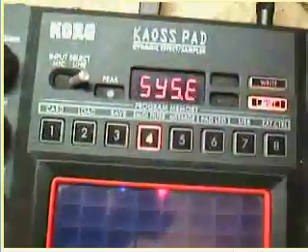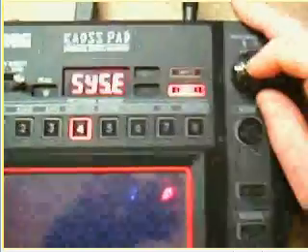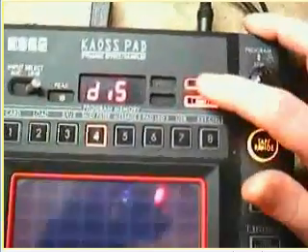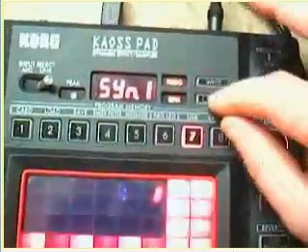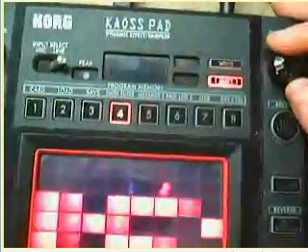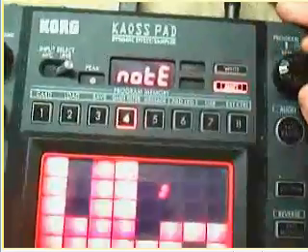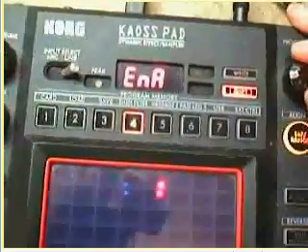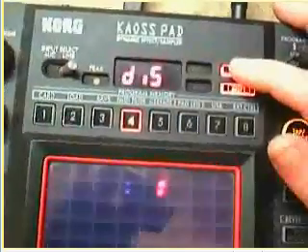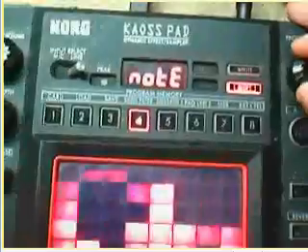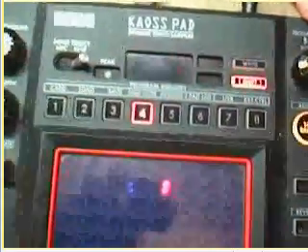In this case, I would recommend disabling everything except what you need. So go ahead and press the knob down on System, switch it over to Disable, and press Right. Then you're going to have to go back in, Shift 8, Shift 4, go to Note, or whatever comes up next on yours, push it in, and change it to Disable. And repeat that for everything except for CC. Command control we want to leave as enabled.